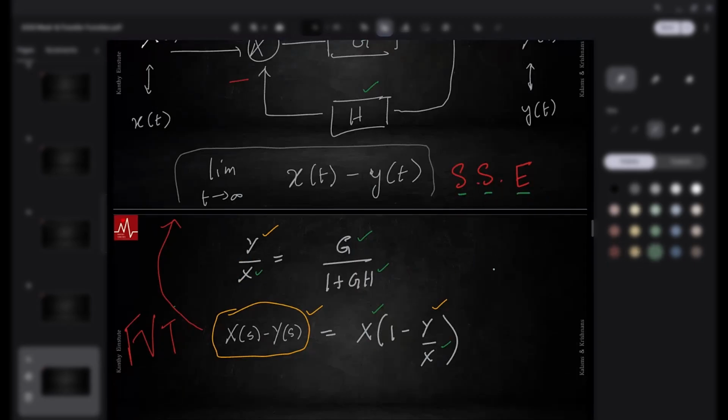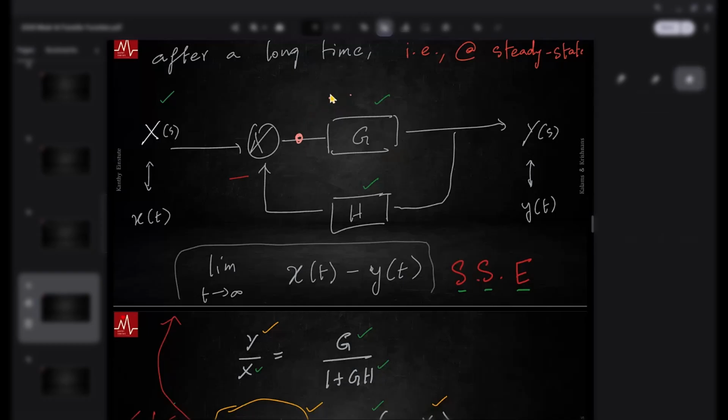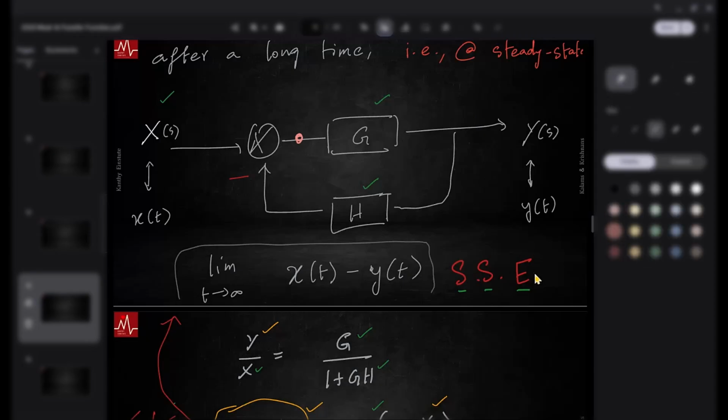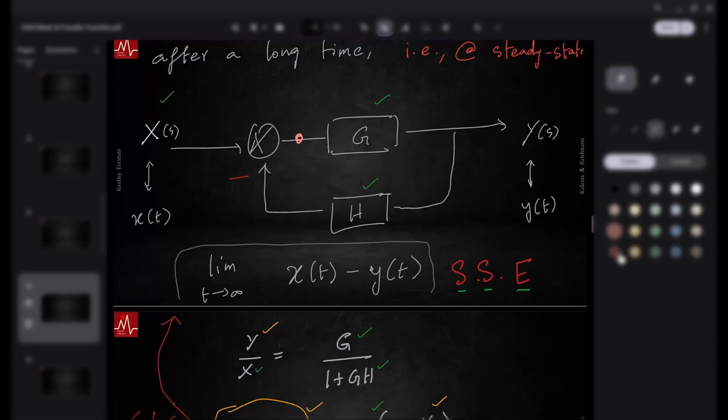Okay, and there are a couple of nuances on the steady state error. There is an actuating error, right? The error is a signal that shows up that we typically call actuating error. There are some subtle nuances, but this is what we intend, what we actually get. That difference is the error, and this specifically is the steady state error. And in a GATE question in control systems, they will ask you the steady state error, given X, G, and H.